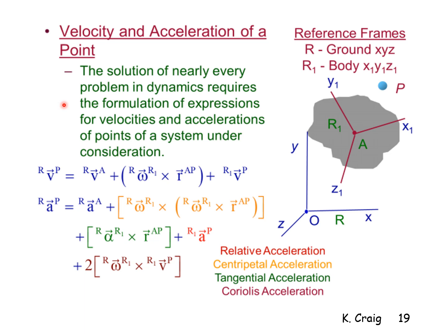The justification for plane motion is that most machines use mechanisms. Machines are made up of mechanisms that are, for the most part, plane motion mechanisms. Four-bar linkages, multi-bar linkages, slider cranks are all plane motion mechanisms that combine to form plane motion machines.